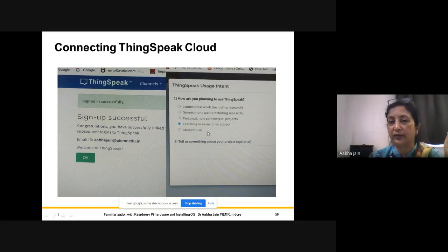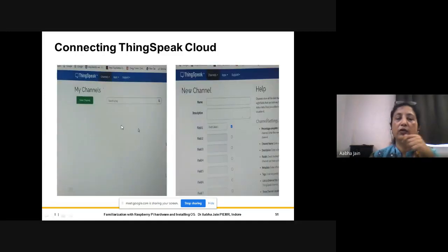And sometimes, in fact always, it asks for what purpose you are going to use this facility, ThingSpeak Cloud facility. So choose appropriate information. Since we are teaching, I choose this one. And then they allow me to create my own channel on their cloud. So this is my channel. I choose this new channel because I want to create a new channel. And when I click on this new channel, this screen appears on my screen.